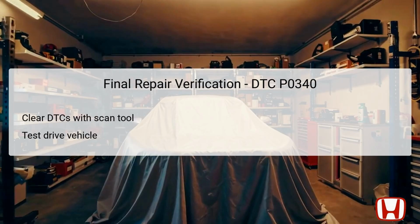After completing the necessary repairs or replacements, it's vital to verify the effectiveness of the fixes. This begins by clearing any DTCs with a diagnostic scan tool to reset the PCM's memory. Following this action, a test drive is essential to observe the engine performance under normal operating conditions.